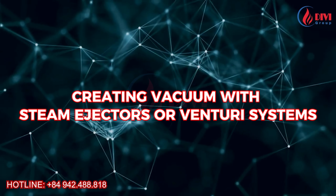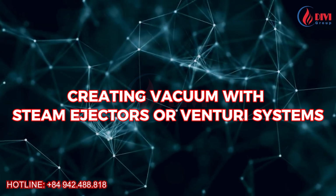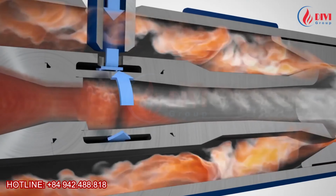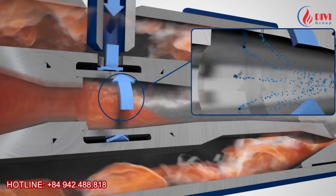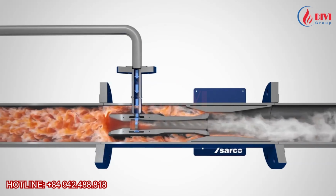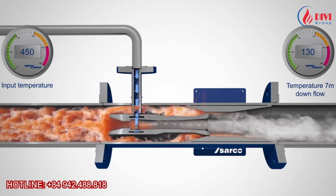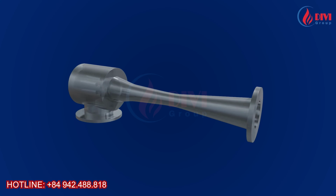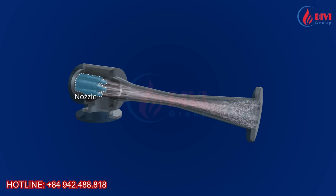Application 6. Creating vacuum with steam ejectors or venturi systems. As steam flows through a pipe at high speed, it carries a tremendous amount of kinetic energy. With the proper equipment design, this high-speed steam flow can create a low-pressure zone that draws air or vapor from another space. These devices are commonly known as steam ejectors or venturi systems. A steam ejector uses a high-velocity steam or gas stream to create suction. A venturi works by accelerating the fluid through a narrow section, creating a low-pressure region. This suction effect can be used to create a vacuum inside equipment or enclosed process vessels.